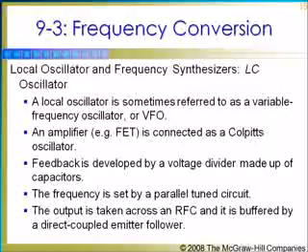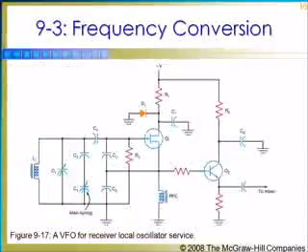Even inductors, which are relatively stable, have slight positive temperature coefficients, and special capacitors that change little with temperature are essential. Usually, negative temperature coefficient ceramic capacitors are selected to offset the positive temperature coefficient of the inductor. Capacitors with a mica dielectric are also used. A diagram of a VFO for receiver local oscillator service. C3 can be replaced by a varactor reverse biased to make it act as a capacitor. Then a potentiometer applies a variable DC bias to change the capacitance and thus the frequency.